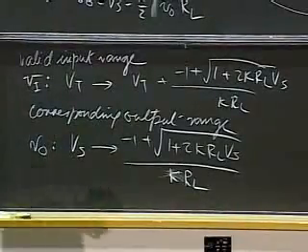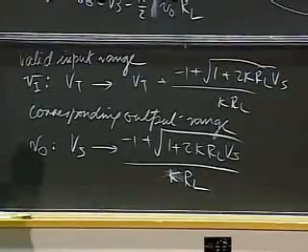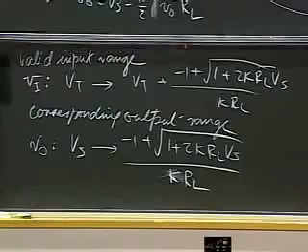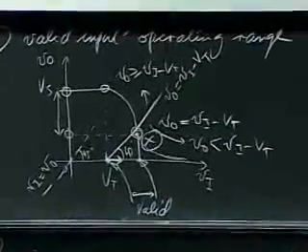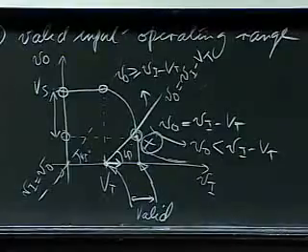Let me go back and quickly show you a little MOSFET amplifier circuit, so you can stare at a real transfer curve yourselves, and convince yourselves that roughly at the point shown in the curve up there, the MOSFET indeed goes into its triode region and begins heading out of its saturation region.